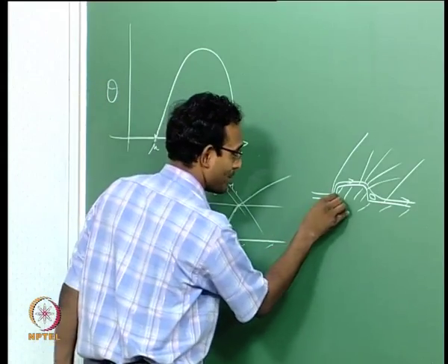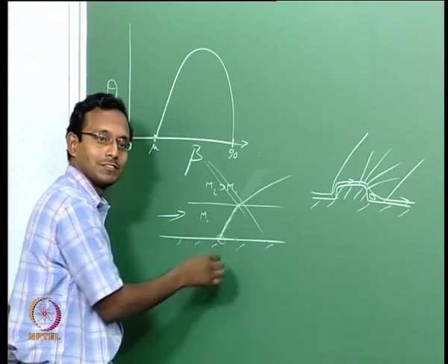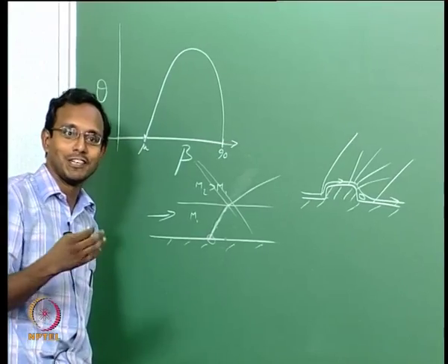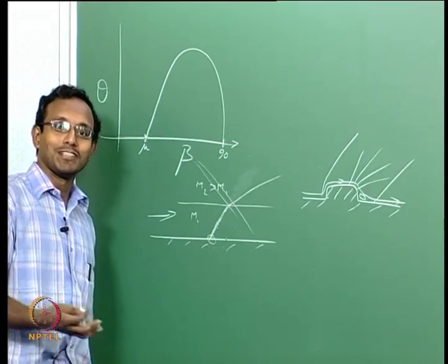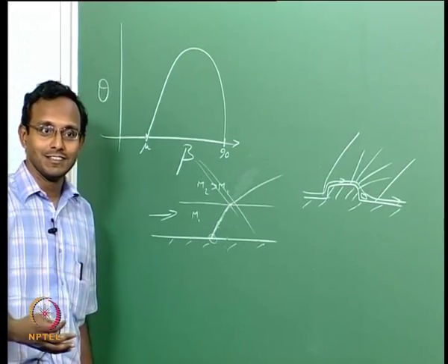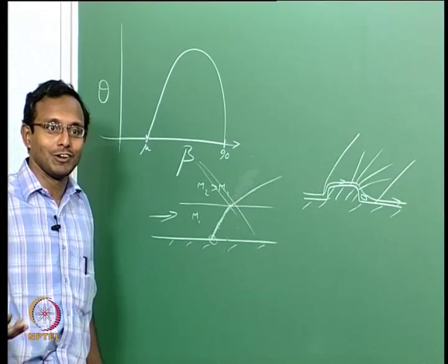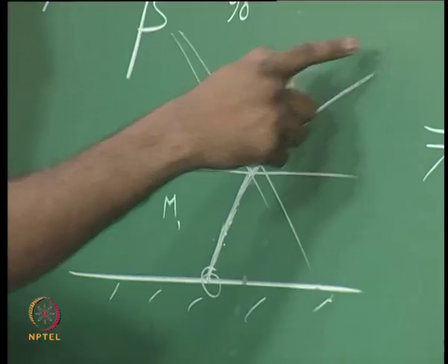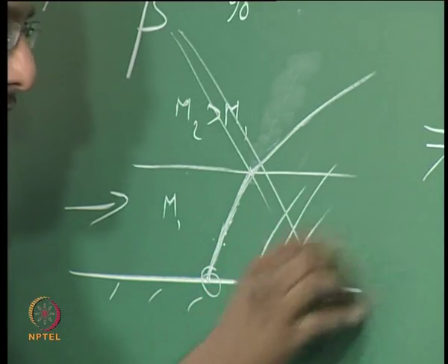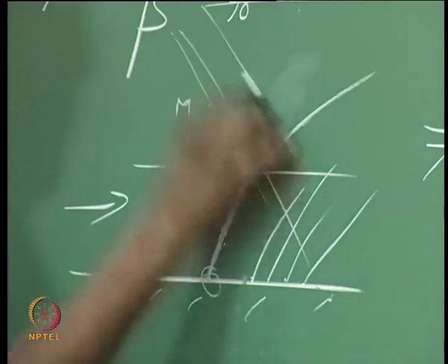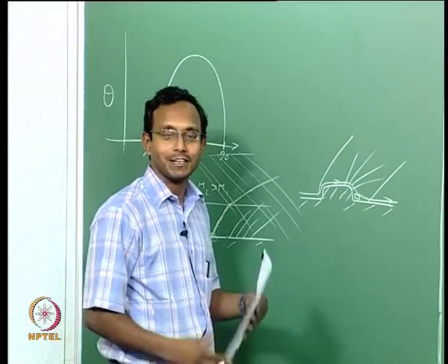Everybody will just put a very tiny bump on the wall, typically something like this, and now I can track this. This is a very small density change, and that can be tracked by shadowgraph or Schlieren experiments, and so I can now say that this is my Mach line. And if I do my method of characteristics analysis, I can get the same line because it is a characteristic line also. Mach wave is a characteristic wave, we already figured that out. So they are all going to match. If I put a whole bunch of them, ideally I will get my method of characteristics grid. If I put the same thing on the top wall, I will get the whole grid. That whole mesh you will get from there directly.